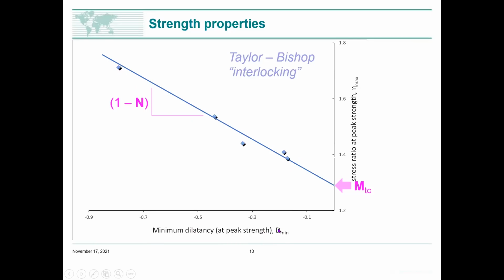And remember, I was talking about work conjugate invariance, where you don't get a free choice on how you measure dilatancy. It has to be this volumetric strain invariant divided by the distortional strain invariant. So you need to keep your wits about you when you calculate that. And rather than doing peak friction angle, we do everything as a stress ratio. So that's Q over P.